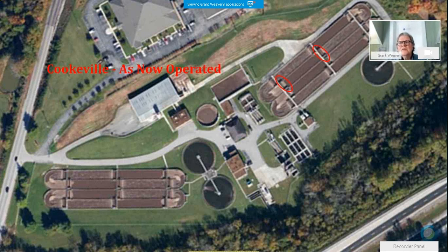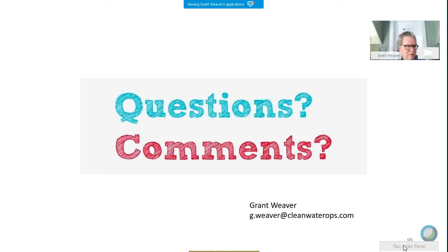In the next 4 hours, 2 in a row to create a strongly aerobic zone. So every 12 hours, we just went through 12 hours, and the next 12 hours we start all over again with the first 2 up at the top. So that's created a major improvement in nitrogen removal, and improvement in phosphorus removal, and reduction in their electric bill of $250,000 a year, which I'm sure went immediately to raises for Tom and John, if only. They deserved it.